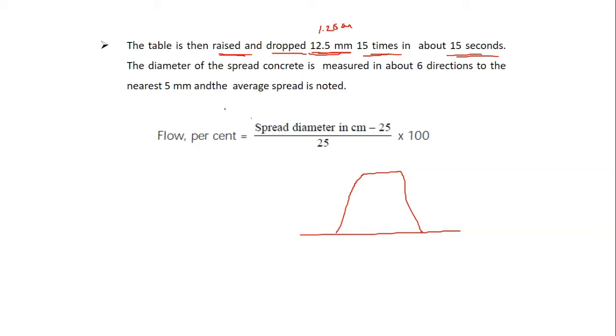What happens is that because of the vibration it causes, the concrete is going to spread over the table, right? So now the spread diameter of the concrete is measured.